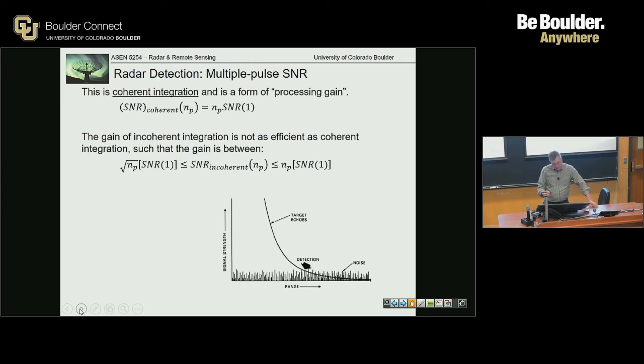And the idea is that, one idea is that for every target position, there's going to be some measurement uncertainty. What's this measurement uncertainty relative to the fluctuation of the noise? And if we do multiple pulses, since the target hasn't moved very much, you're going to get several samples of noise, you can beat down the variance of this noise, and then hopefully this noise variance will be smaller than the variance from your target.